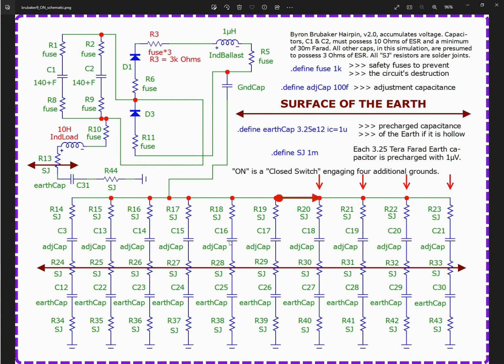So you're not going to find a tenth of a picofarad to shop for it online. So you just have to buy 10 picofarad capacitors and string them up in series so that the total capacitance of all 10 of them is a tenth of a picofarad. Of course, you're going to have solder joints between them, and that's going to add resistance, and I don't have that in this simulation, so you may get different results. You may not even get over unity. So maybe you'll have to construct your own tenth of a picofarad capacitor from scratch. Be that as it may, there are ways of doing that. There are people online who tell you how to do that.